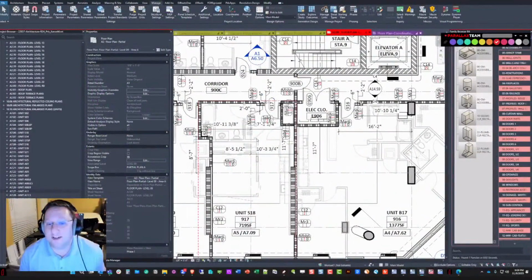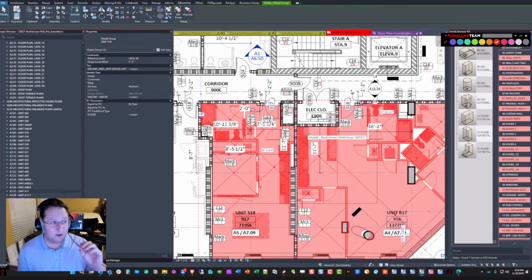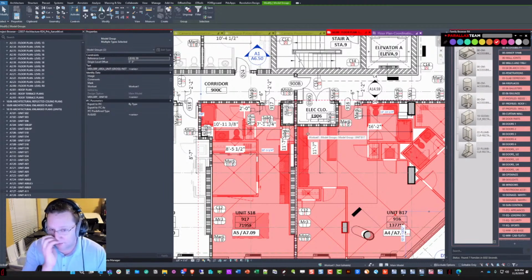That's a cool tip for the exterior wall. How about demising walls? What was the approach here, and what approach have you seen work? Yeah, that's great. So demising walls for us never go in the groups. They're always separate. And I'm going to terrify every Revit user in the chat in a second. Oh boy. So we don't ever endorse putting demising walls in the unit groups. And of course, that means the corridor doors are not part of the groups as well. That's all part of what we'll call the core and shell.